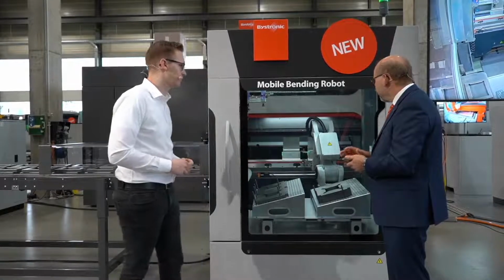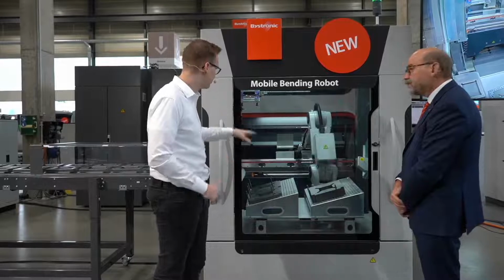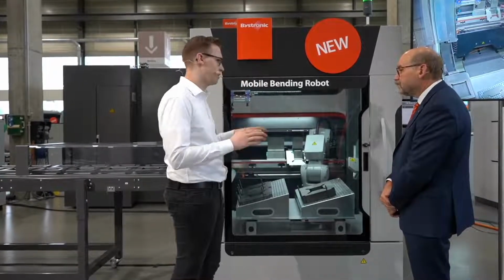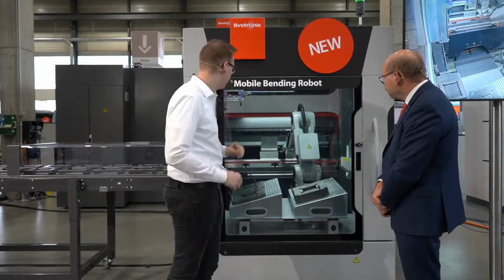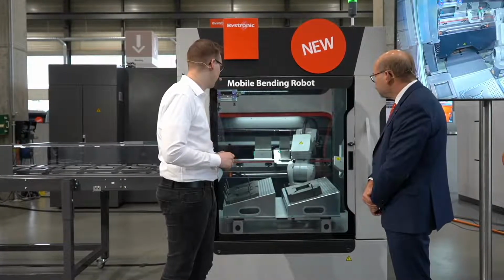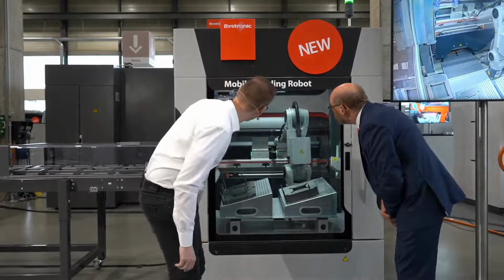Okay. Can you explain the cycle, what it does? Yes, of course. So at first you saw it grips the part, in this case with a magnetic gripper. Then we have our alignment station. With the alignment station we make sure that we grip the part in a perfect way. And then we start with bending. Right now we have 8 steps of bending, and we are also able to follow the part with our grippers and lift the part with our grippers. And if we have to change the parts, then we can also use our regrip station at the left upper side of the machine.